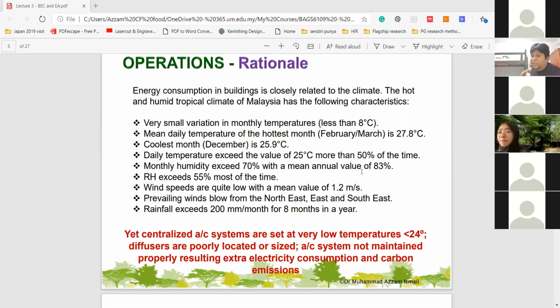So relative humidity is read in terms of percentage. In an office building, you want it to hover between 45 to 55 percent. Anything more than that will be a bit too damp. Anything lower than that will be too dry. Your mouth will start to dry. Your eyes will dry up. Your nostrils will dry up as well. So you need to get a balance somewhere. So your air conditioning, you set it to a certain temperature and certain kind of mode that will allow for about 50 to 60% of humidity in the room.